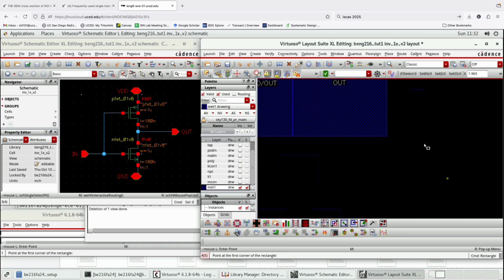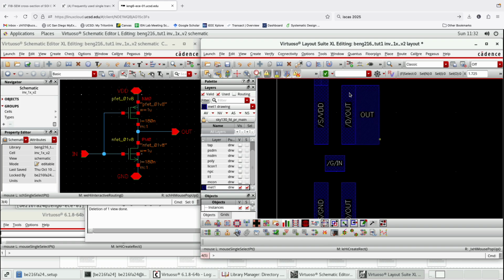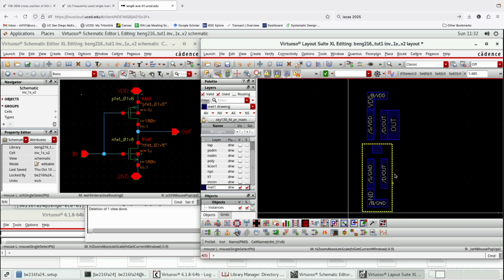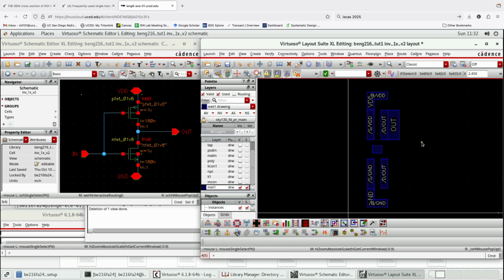rectangle slightly larger. So here I just made this connection, which extends this drain of the PMOS further. And there we go. There's nothing that the DRC is complaining about so far, which is good. What I then need to do is, because I want to make the circuit very symmetric with respect to the x-axis, I would also want to do the same thing down here on the NMOS.